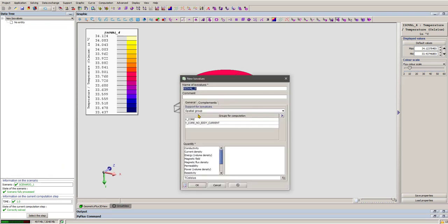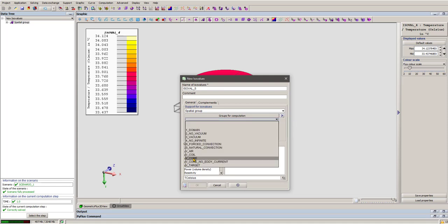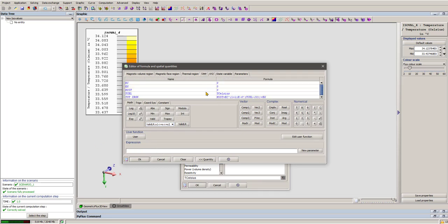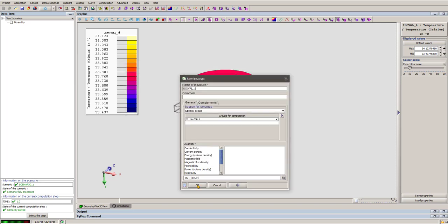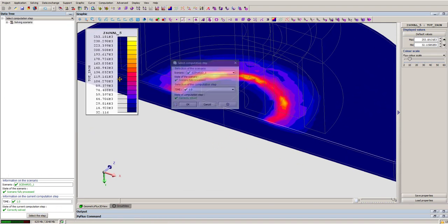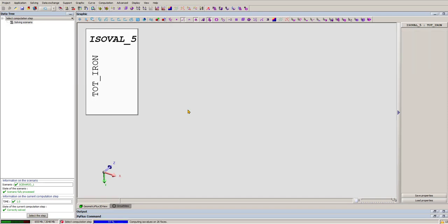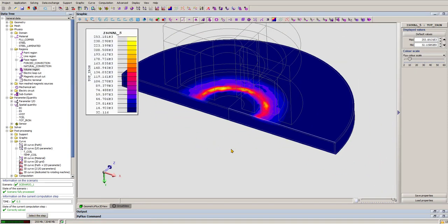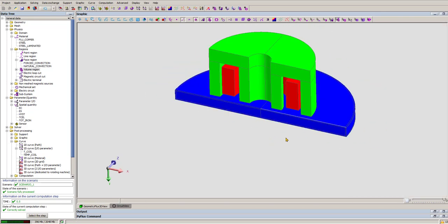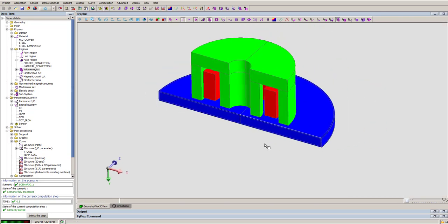What we can plot as well, maybe making a clean selection again, is to select the target and plot the iron losses we imported. It's also possible. So one can see if there is a modification, or if there is no big impact, and it's normal because the change is not very impressive here. Yeah, so this is how to use iron losses in the thermal computation.